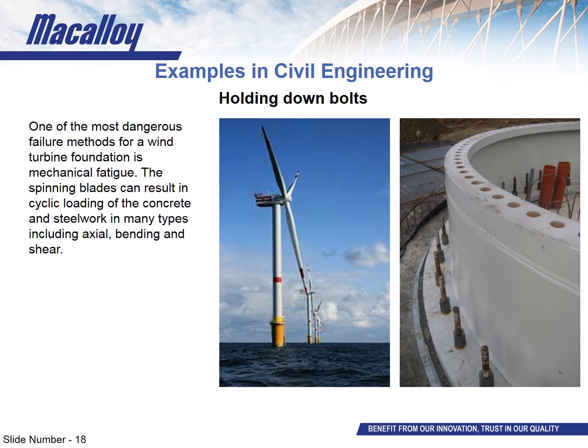You can see this in the right-hand image. As the wind buffets these turbines and those blades swing around, the turbine itself wants to rock. Now these forces are taken out on these bolts, and like bridge sections are a combination of shear, bending, and via prying some axial force, giving the potential for that massive stress range.